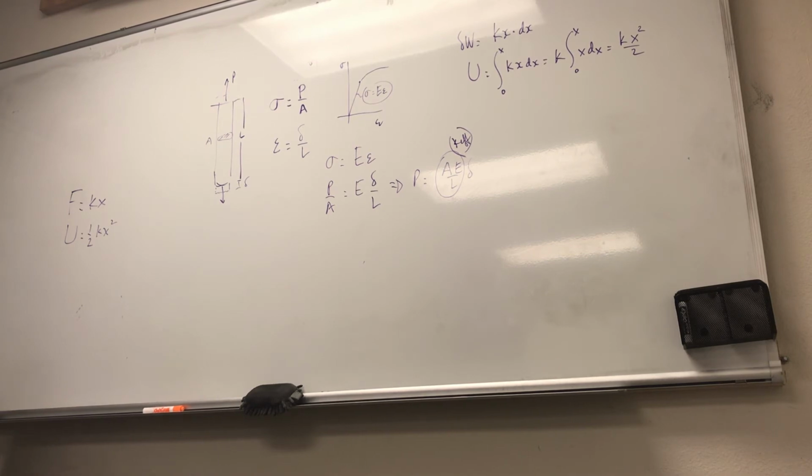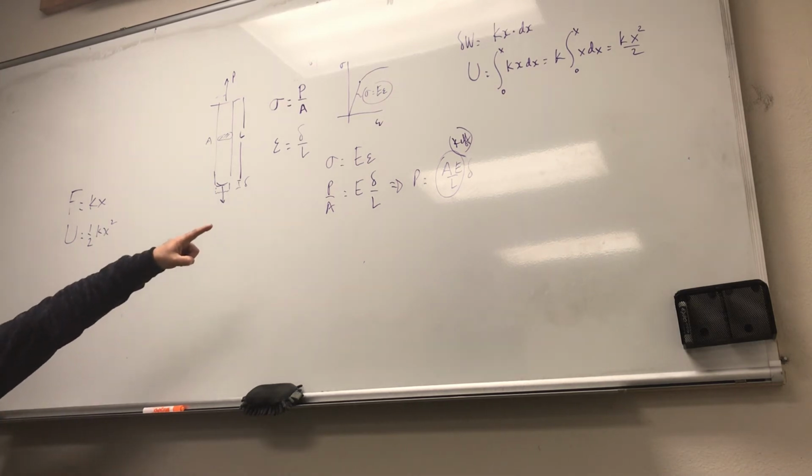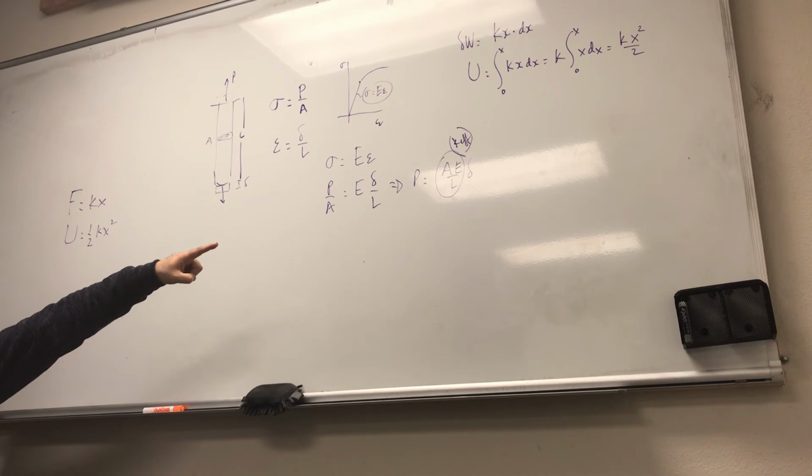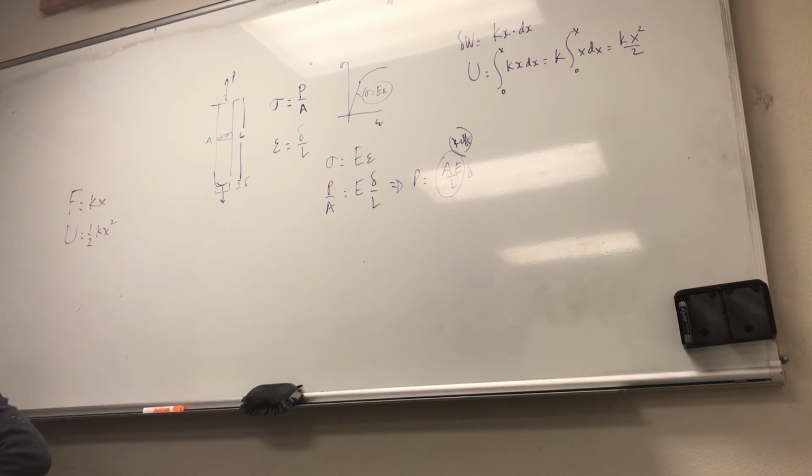Now, the only thing is you rewrite this equation in the form of what? You know that K is equal to what? It's the load divided by delta, right? So you write K as W divided by delta, and here you get delta from here, which happens to be 3EI over L cubed. So what does this mean?